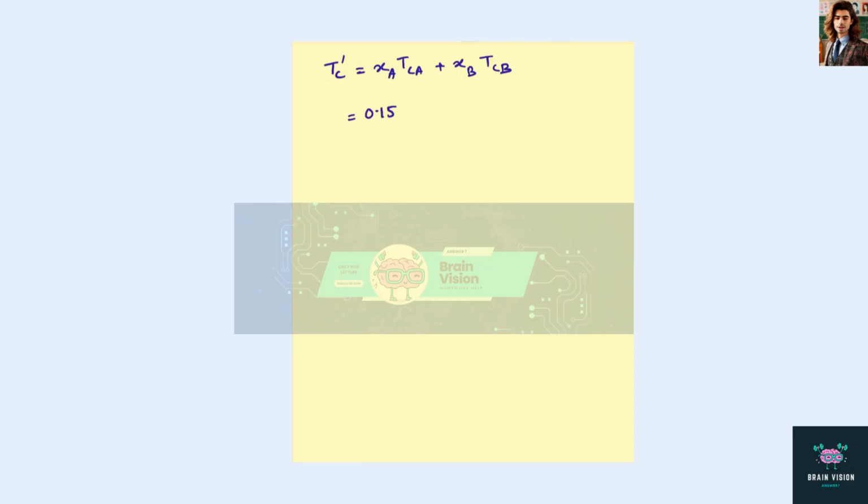Here the mole fraction of hydrogen is 0.15 and its critical temperature is 41.4 Kelvin, and the fraction for 1-butene is 0.85 and the temperature is 419.6 Kelvin. Therefore we get the pseudo-critical temperature as 362.9 Kelvin.